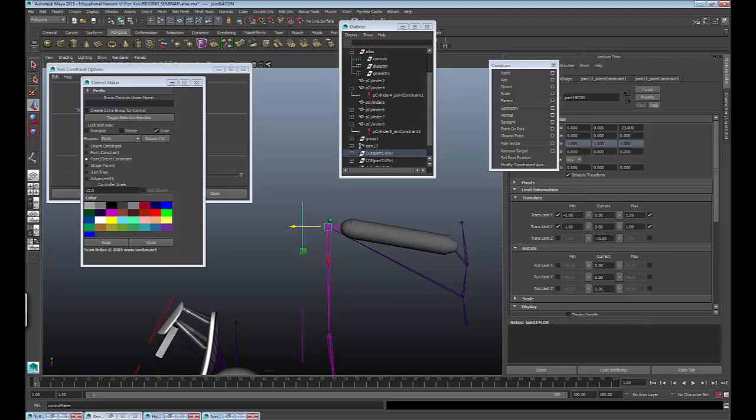That's a negative, so I'm going to use this arrow to shoot that value into the negative box. And then I'm going to go positive to, you know, before it rips apart there. So that's about 15, we'll round it down. And I'm going to shoot that over to my positive box. And then I'm just going to turn it on now. So now when I move this around, it'll stop there, it won't go any further. And then you just do the same for all of the other axes.